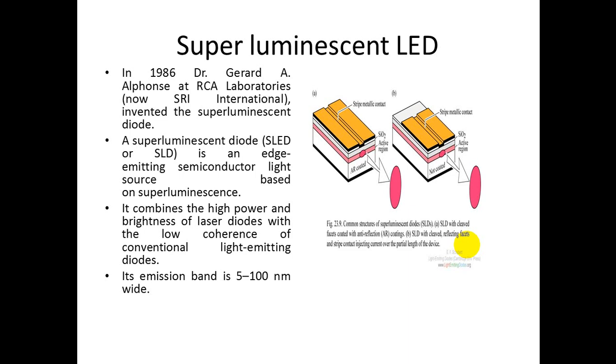Superluminescent LED. A superluminescent diode, SLED or SLD, is an edge-emitting semiconductor light source based on superluminescence. It combines the higher power and brightness of laser diodes with the low coherence of conventional light-emitting diodes. Its emission band is 5 to 100 nanometers wide.